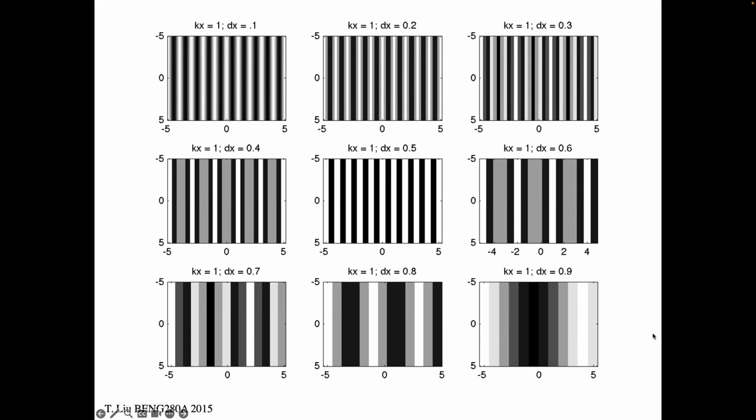causing this low frequency modulation. You can see this a lot when you have a screen door or a pool screen or something like that, and then behind it, there's something that has another screen or another high frequency, and you take those two screens, and they're both sampling rates, right? And you just move one screen to, like, angle the screen to the other, then you're changing the sampling rate, and you'll see these very low frequency patterns emerge between those two objects, right? Everybody's seen that, right? You're not crazy. It's just sampling theory.